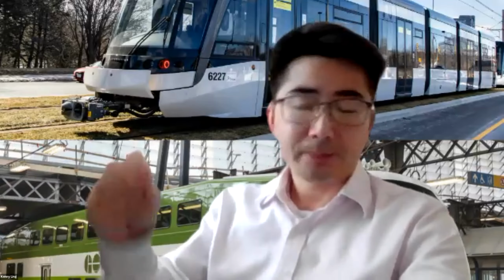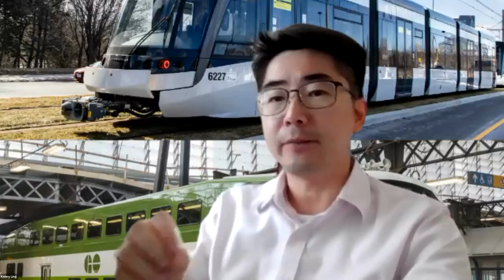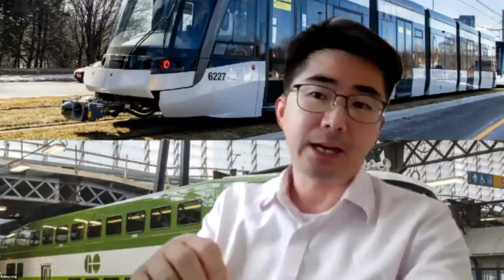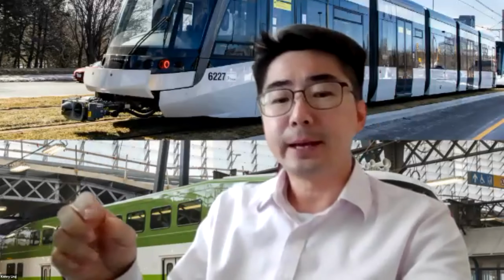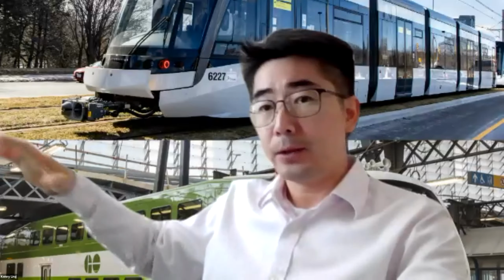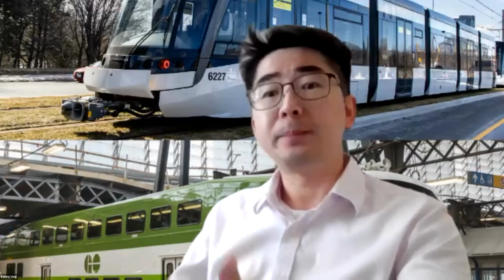So because of the trespassing event, it got delayed by 10 minutes, but then subsequently, because it missed the time slot, you have to wait for another 10 minutes before it can pass that single track location, because it has deviated from the original schedule. So at the end of the day, it's also about how do we control the occurrence of primary delay so that we can reduce all these subsequent secondary delays, and overall improve the OTP, on-time performance.